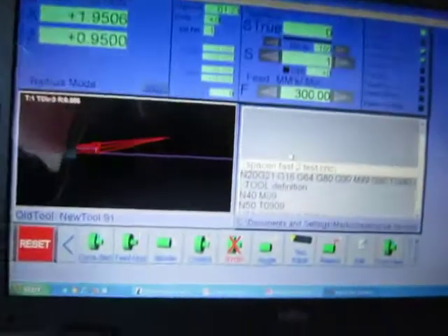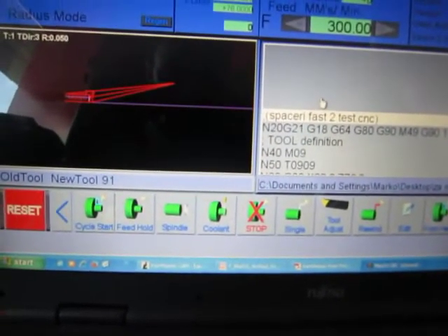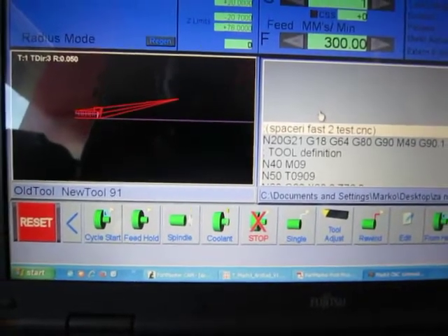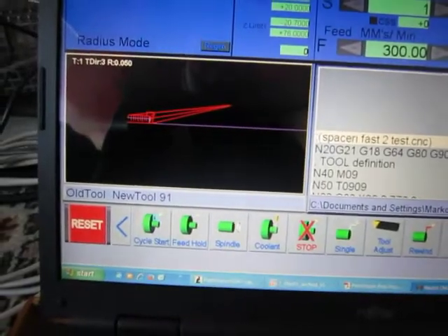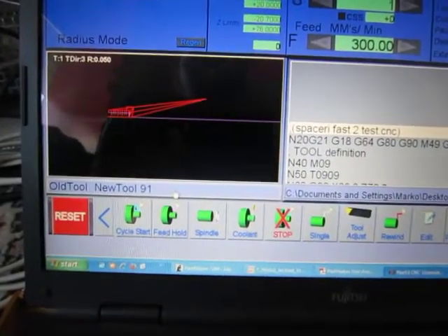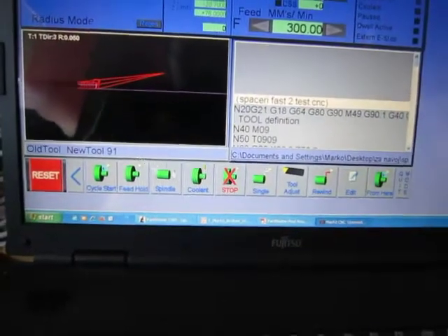So in this situation, when the spindle needs to stop before every tool change, you cannot notice the problem if you selected 1000 instead of 3000 to be the acceleration.